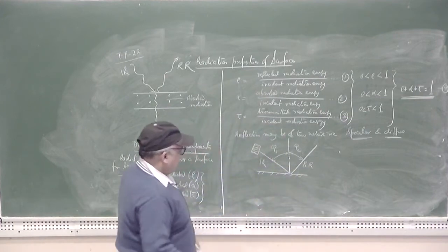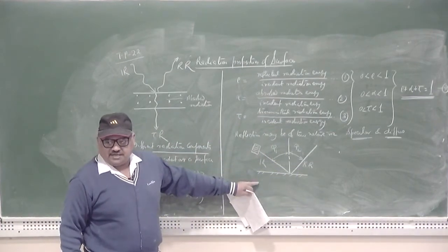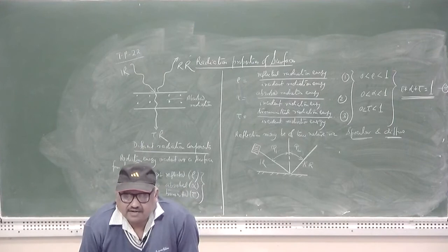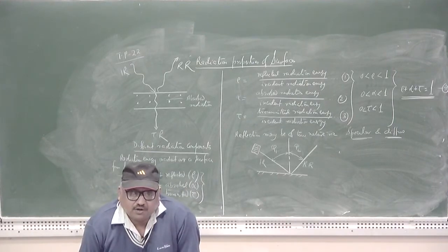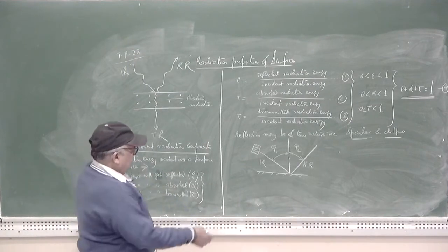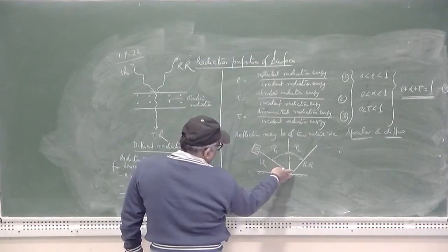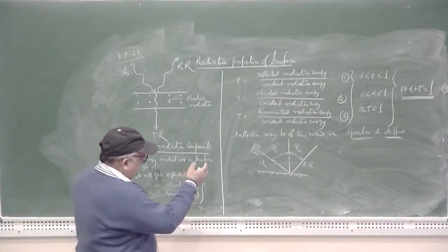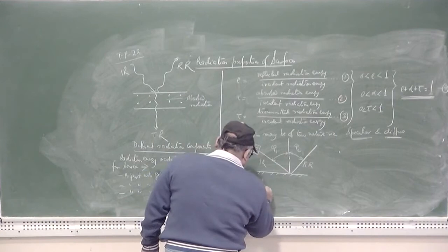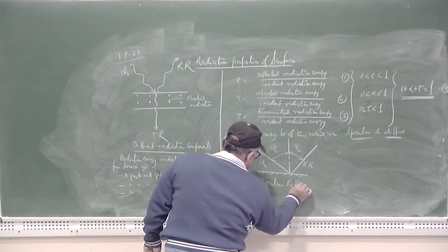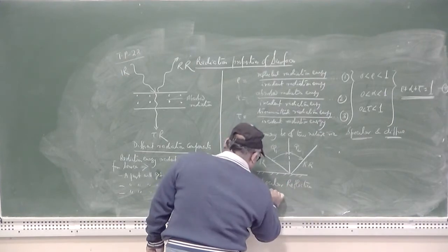This is possible only if the surface has been polished to such an extent that there are no protuberances, no undulations, no defects. Under those circumstances, the law of reflection will be completely obeyed by this radiation with phi 1 equal to phi 2, and such type of radiation is what is known as specular reflection, and this is possible in the case of a perfectly